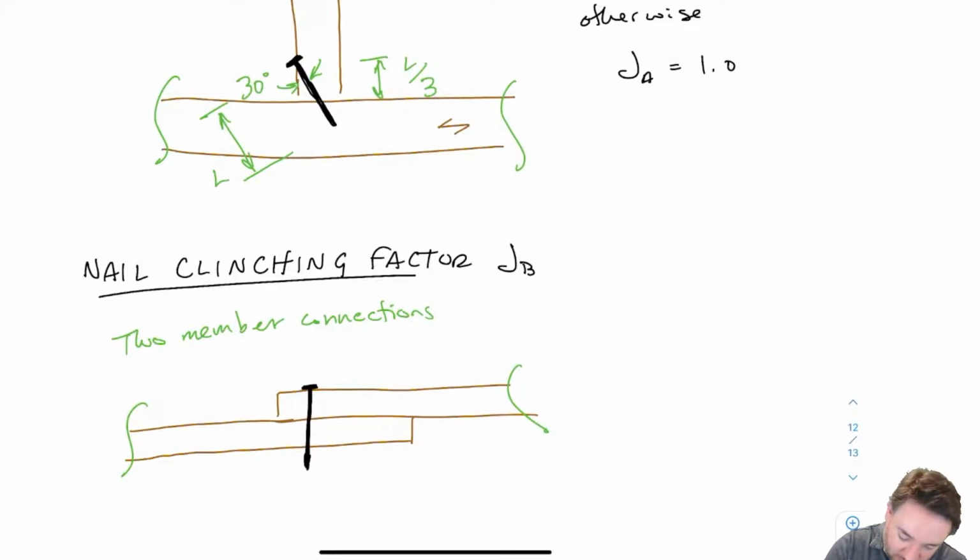And furthermore, after I have that nail that is a bit longer, I can take my hammer and bend down the point of the nail sideways. So basically I nail through, then I go to the other side, get my hammer, and hit the nail sideways, like I smash the nail like this, hammer it, and then basically I tilt down the end. Okay, so what that does is it prevents withdrawal,